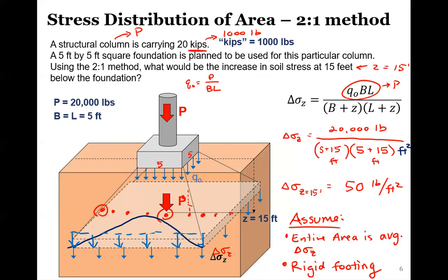You can probably picture if you put a piece of paper on sand or something and then pushed on that piece of paper, you would see bending in the footing and you would see the stress being isolated underneath where you pushed, right? Now, if you took a coaster or a piece of plywood and applied the same stress, that plywood is going to be more rigid than the paper and you would see a different distribution of stress.